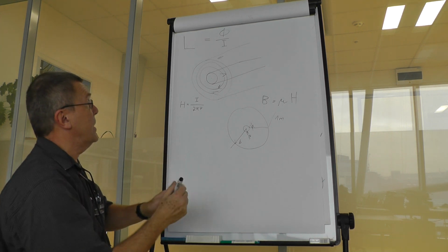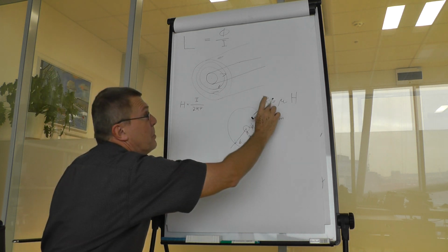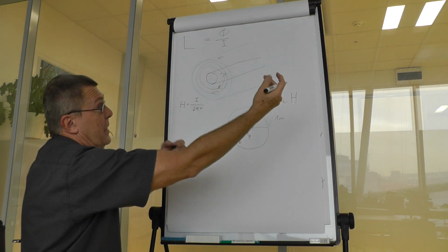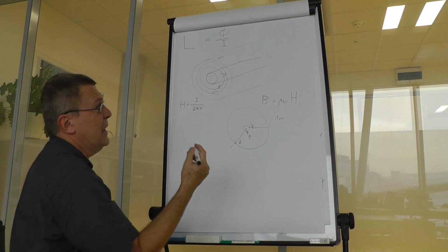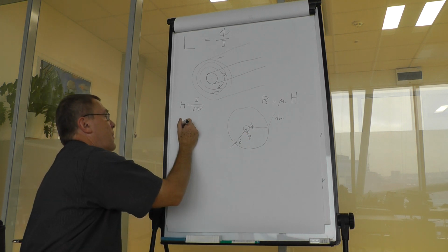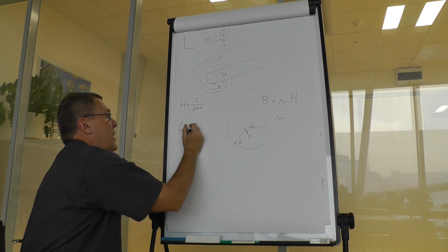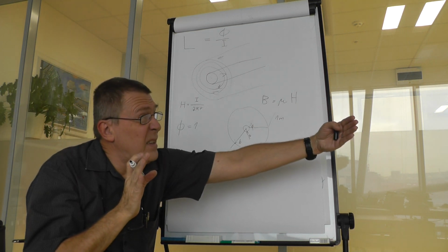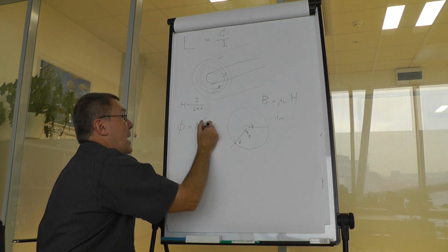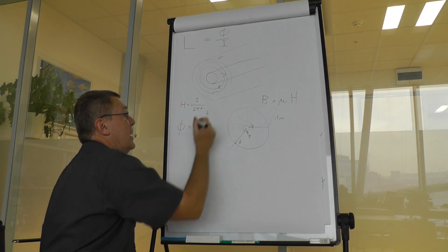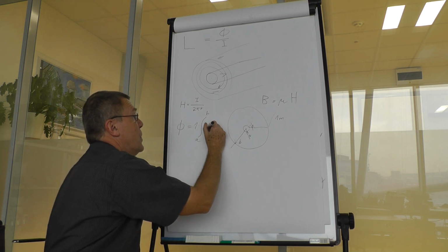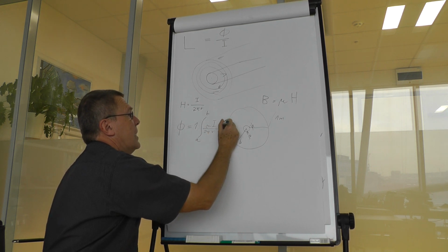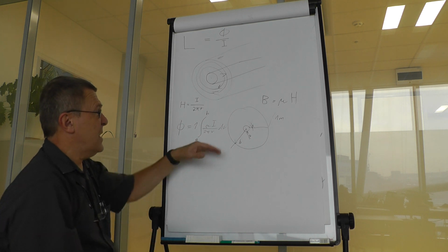Then, in fact, we have to make an integral of B multiplied by 1 meter from a to b dr. So the flux phi would then be, I put here 1, just to say we integrate for 1 meter of length, the integral from a to b of mu I over 2 pi r dr. And this is a textbook integral.